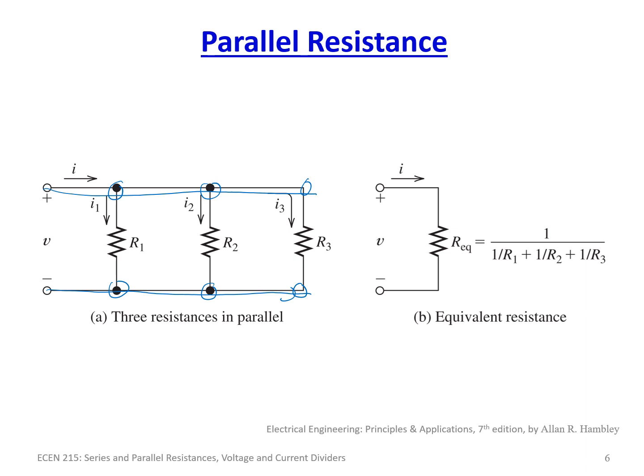Well, it is the reciprocal. So you have 1 over R1 plus 1 over R2 plus 1 over R3. And honestly, this can go to 1 over Rn. So if you have 50 parallel resistors, you will have 1 over R1, 1 over R2, 1 over R3, up to 1 over R50. And that's exactly what it is. Fairly simple.